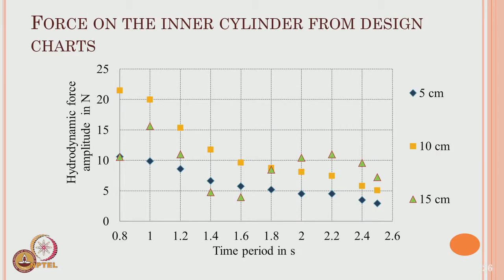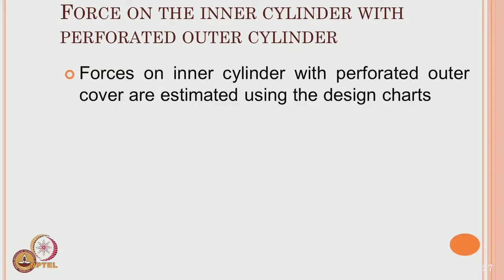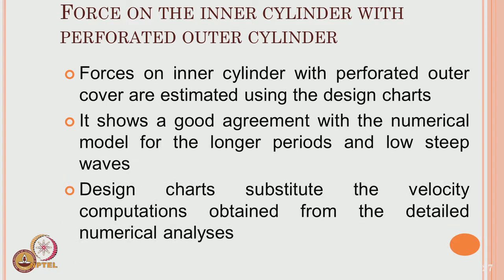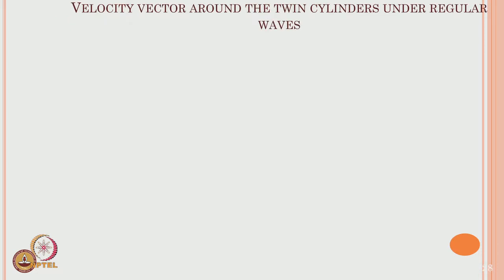We have also plotted the force directly on the inner cylinder from design charts for different waves, in terms of amplitude in the scale model. Then, the force on the inner cylinder with a perforated outer cover estimated using design charts shows good agreement with the numerical results for longer period waves and low steepness waves, not for all. Therefore, it is found that the design charts can substitute the velocity computations obtained from detailed numerical analysis only for a specific range of values.